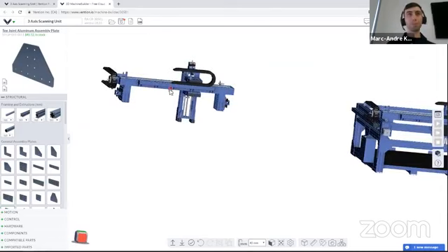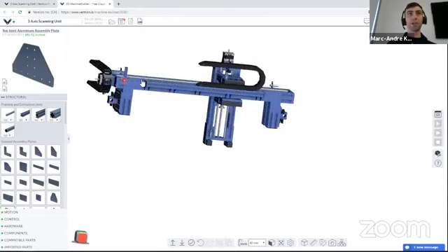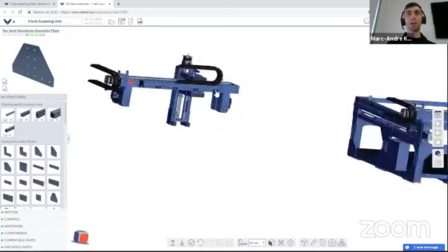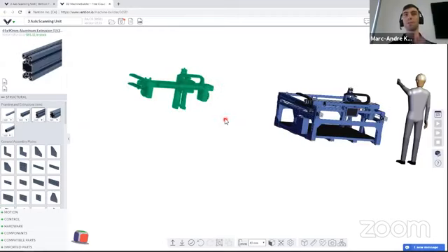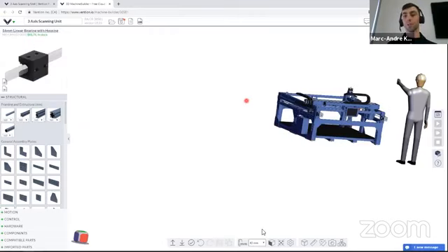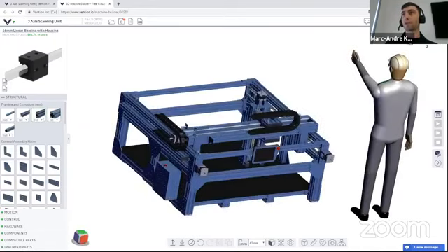Okay, so here I have pretty much all I need to move on this X carriage. And we see that we have a weight of 320 kilos. So the only thing that's left to do is take this carriage and delete it. You can use backspace or delete when you're doing that. So we're going down to approximately 250. So it makes a difference of 70 kilos.